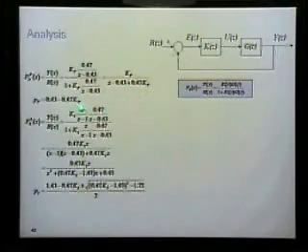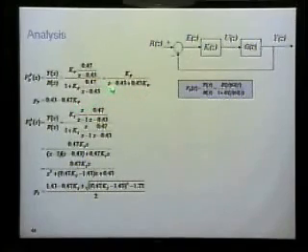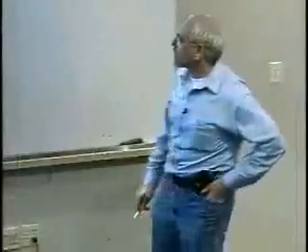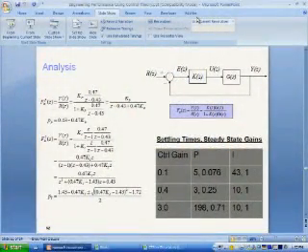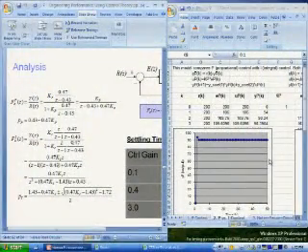So here are our poles. It's the places where this expression's denominator equals 0. So it should be 0.43 minus 0.47 kp for the pole. I'm just trying to give you more of a feeling for how the theory relates.